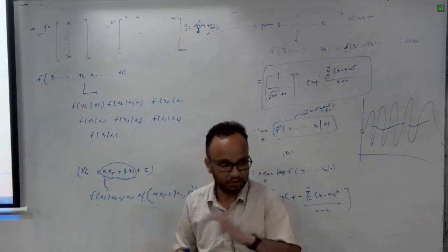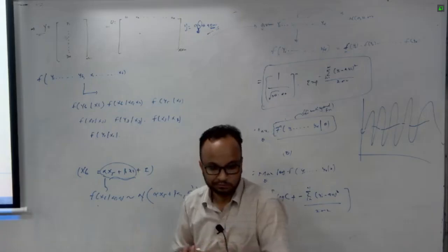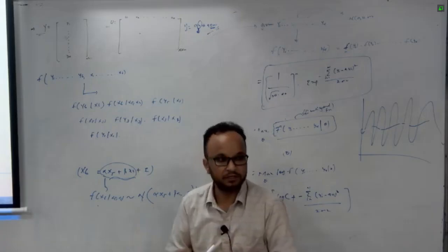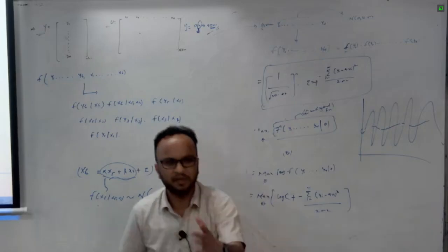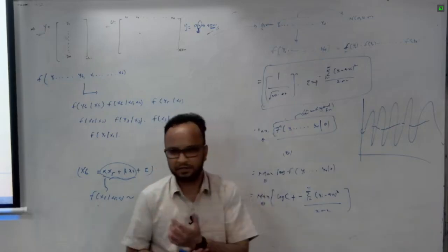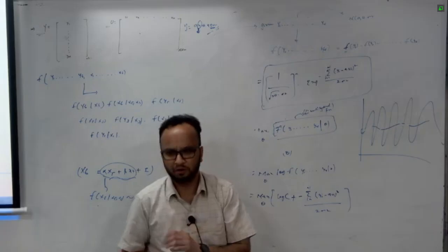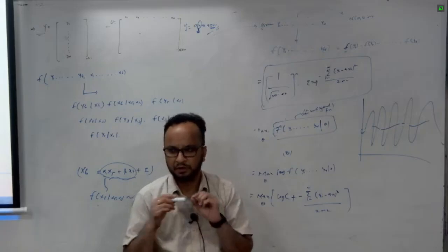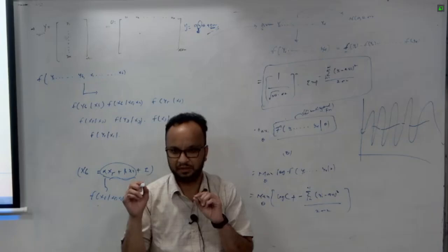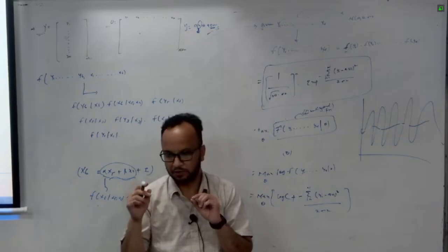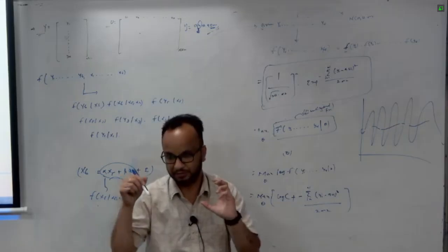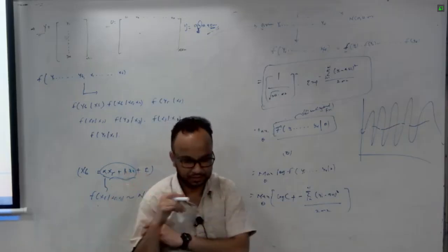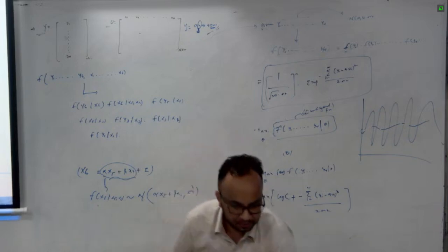What is x and what is theta? You can't get an analytical solution. But I want to solve this. How do I go about it? Expectation maximization is widely used in signal processing, even among electronics students with PhDs, because you have hidden variables there. In Gaussian mixture models or any process where you have hidden variables and measurements and you want to estimate the hidden states of the system, you use the expectation maximization algorithm. So let's see what this algorithm is.